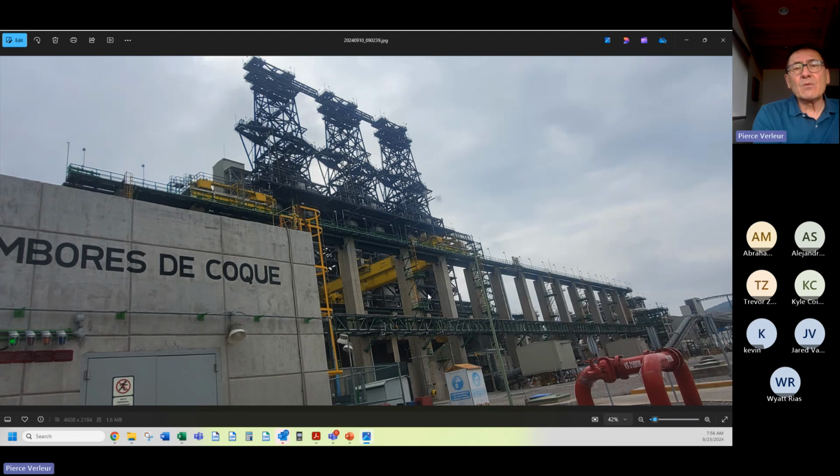In this case, it was an A1000 because the system was originally designed in 2016 before the GA800 came out. It's an A1000 open loop running a PM Yaskawa servo motor, a Sigma 3 servo motor. It's a great application because we've got the thing in there, Yaskawa's motor's IP67. Can you imagine? We put a Yaskawa servo motor inside a decoking tower and it's surviving. Talk about good quality product.